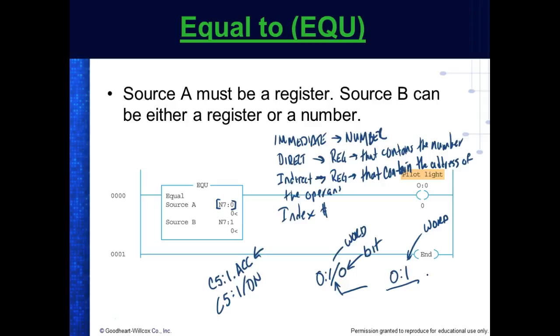And then we have the status register. The status register is a single bit. So when you put the slash D done, you're accessing a bit within the status register. So every counter has 3. Timers might have 1 because timers we have that time base too, right?